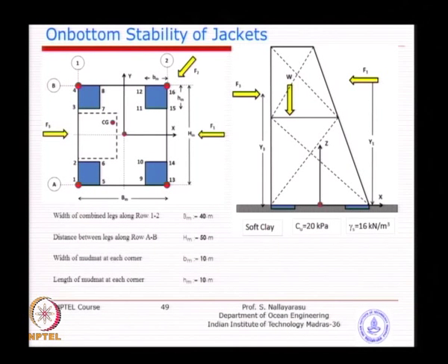F2 may contribute a bigger force in this x direction if its magnitude is larger at that time. So, whether F1 is governing or F2 is governing, we will not know unless you do a simple resolution of force and find out the component of F2 in the x direction or y direction. In any case, if the component in the y direction is more, you are not going to have much problem, because the COG is on that side and may actually help you.